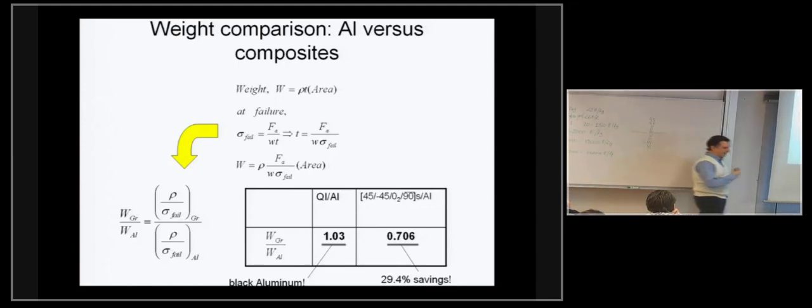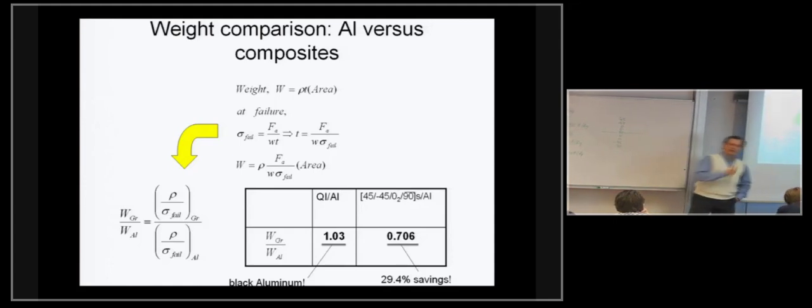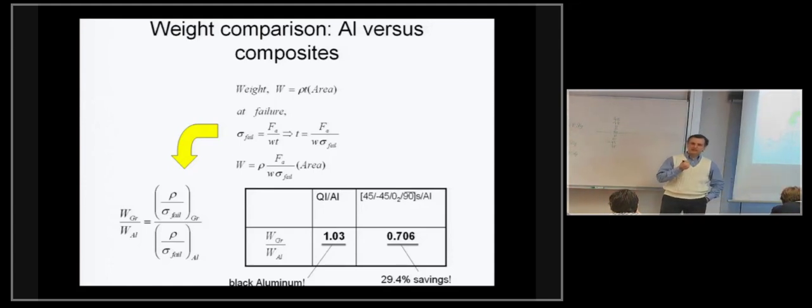So all of a sudden, the need to come up with the correct stacking sequence that will really take advantage of the composite capabilities becomes very important, because if you don't do it right, you will end up with either the same weight or, God forbid, even higher weight.